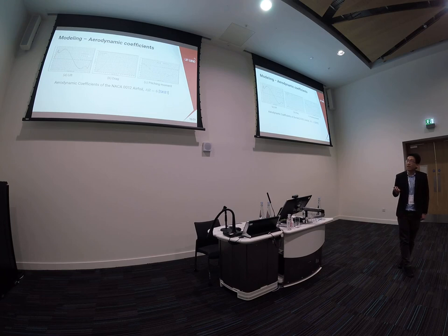For the post-stall region, it looks like a periodic function of the angle of attack. For the drag force, it shows similar behavior: a linear function, and the post-stall is like a periodic. And for the pitching moment, a linear function is enough to fit.